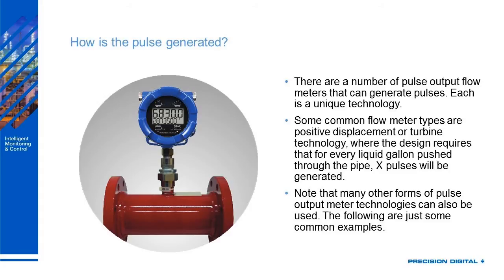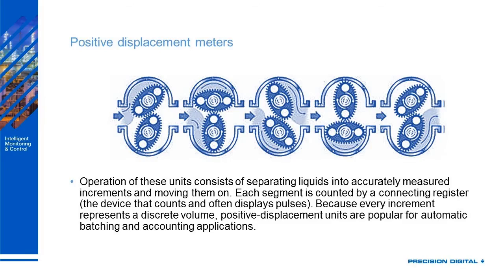All those other types of technologies that are out there, like rotary encoders and linear measurement devices, function on basically the same concept: 1 pulse is going to equate to 1 amount of rotation on my rotary encoder, or 1 pulse is going to equal a certain amount of feet traveled on a conveyor belt. Let's take a closer look at how that might happen.